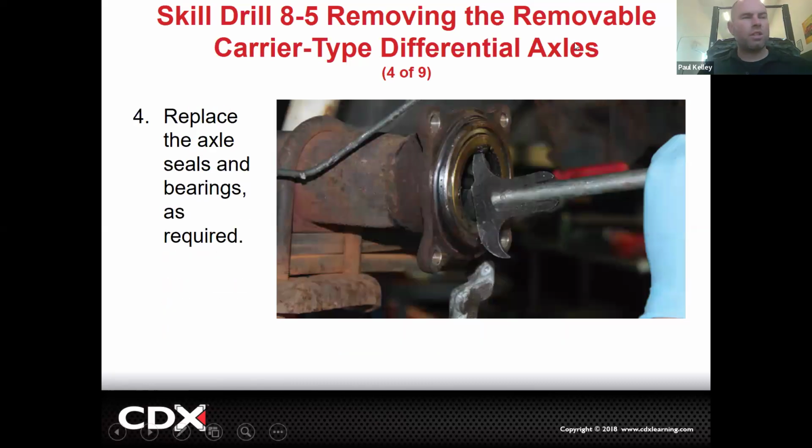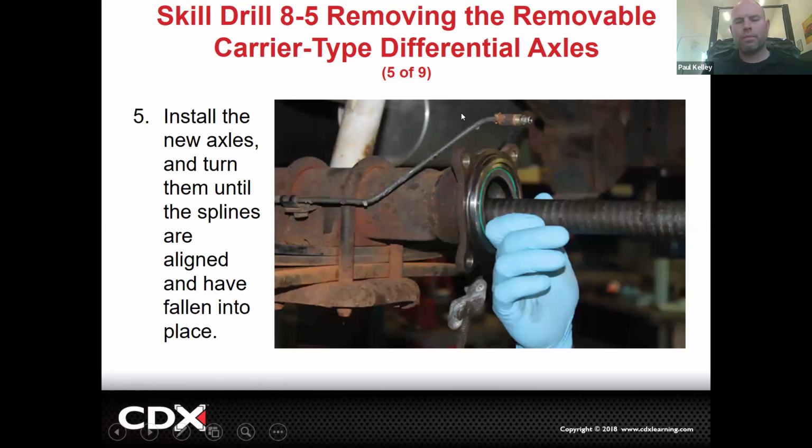But you'll notice there's no bearing behind the seal. The bearing is the bolt-in part. In that way, that's why these are a little more heavy duty. The bearing's really sitting, it's bolted to the flange. Cool. And then you can see that's got the new seal in.